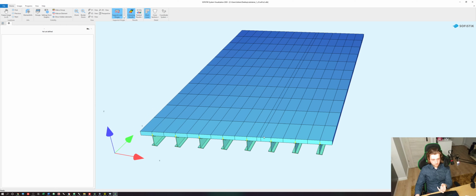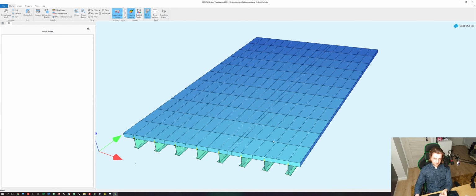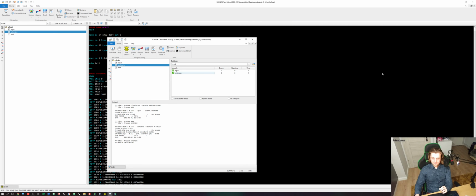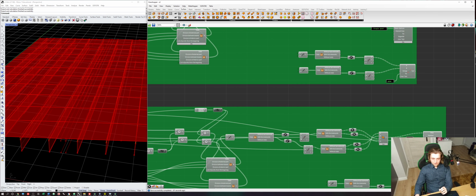And as you can see, this gap was fulfilled. Now, just for better meshing, we will raise the density of the mesh along the bridge, because I think those quads are too rectangular. There should be more square ones or something like that. So let's go here.